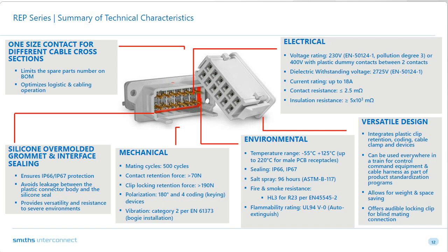And in one of my previous slides, I talked about the different failure mechanisms, right? And I talked about humidity. Now, humidity deteriorates the material properties over time. Another part of the failure mechanism is that it causes galvanic corrosion of the contact. And particularly when the humidity level is above 50 or 60%, the failure mode of corrosion sharply increases.